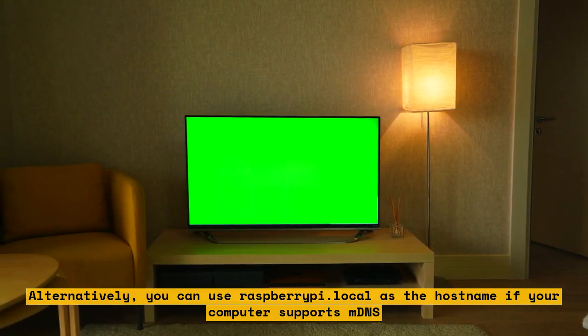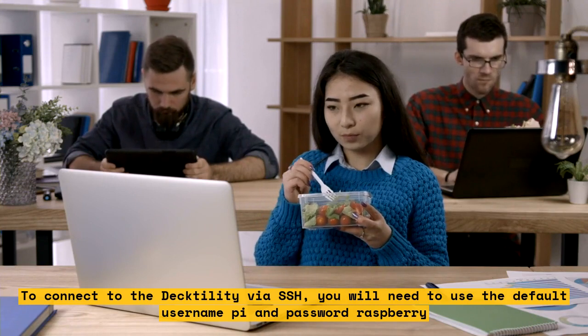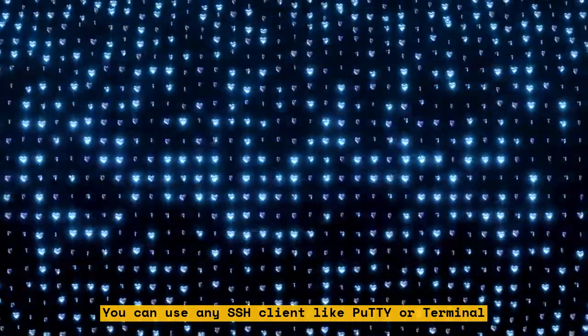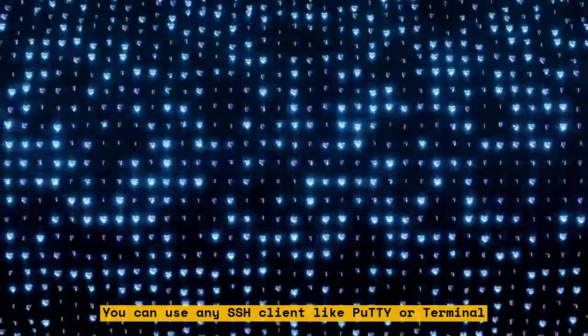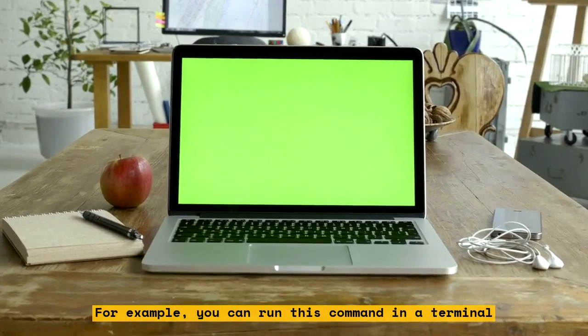To connect to the Decktility via SSH, you will need to use the default username pi and password raspberry. You can use any SSH client like PuTTY or terminal. For example, you can run this command in a terminal: ssh pi@raspberrypi.local.